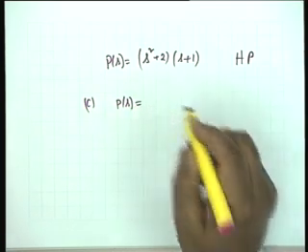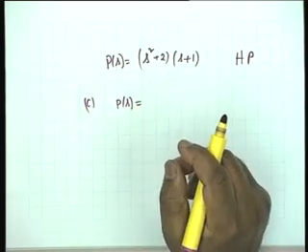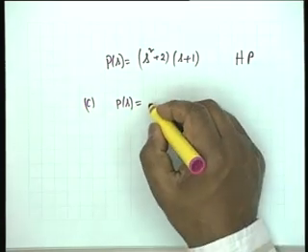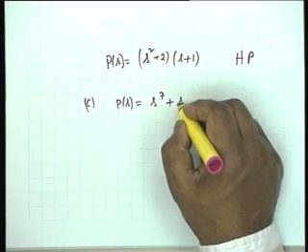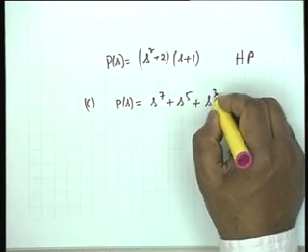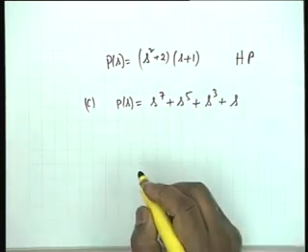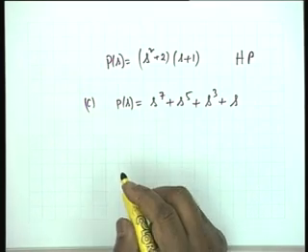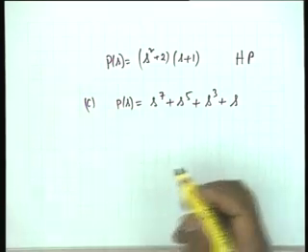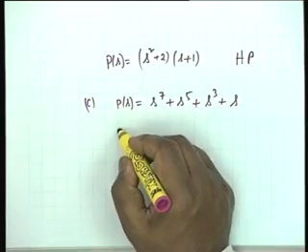Can anyone tell me by looking at b whether it is Hurwitz or not? Because there is a missing term. Okay. C is a purely odd polynomial, and therefore we have to use P prime of s. P of s is s to the 7 plus s to the 5 plus s cubed plus s. This is a purely odd polynomial.